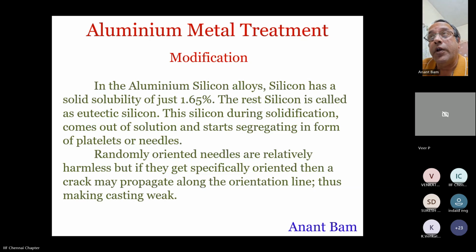Now, in the earlier explanation, we saw that there are 7 grams of silicon in 100 grams of liquid, out of which 0.82 grams got solidified along with a total of 50 grams of solid. So in the remaining 50 grams of liquid, which is a part of the slush, we have 6.18 grams of silicon.